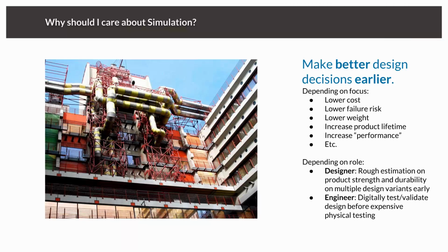And when it came to the point where they had to design the HVAC system, they used the best practices and formulas and standards which were available. And in the end of the day, it came out that the whole HVAC ducting system was much underestimated. The problem was that this ducting was integrated into the core of the building, which means it was not possible to increase further the diameter of the HVAC system by just replacing the ducts.